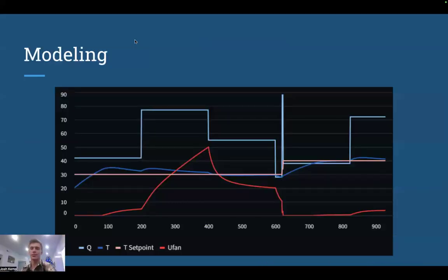Yeah, and then as a starting point to get our PID controller moving, we performed a step test. And using that step test data, we were able to regress the parameter for forced convection in that energy balance for the TC Lab. And that energy balance is enough for us to have a physics-based model. And so implementing that physics-based model into Streamlit creates a model that lets you change the PID values for Kc, tau I and tau D, and then see how our system performs. And that gave us a great starting point for what to try on our actual PID.